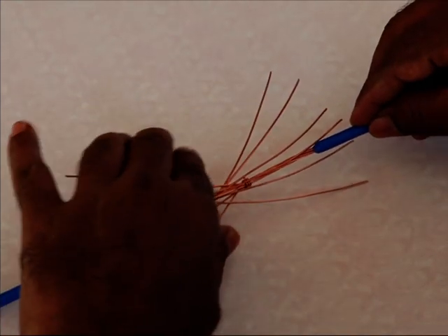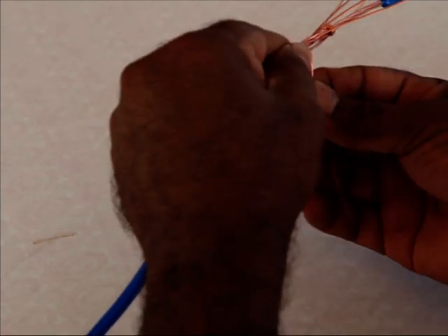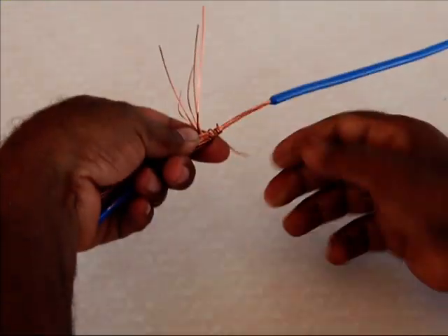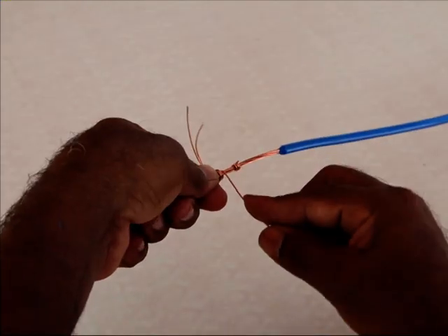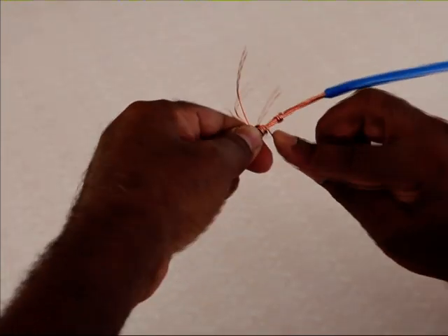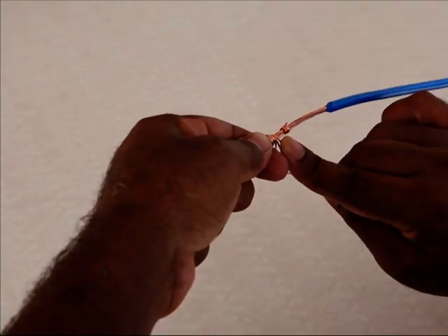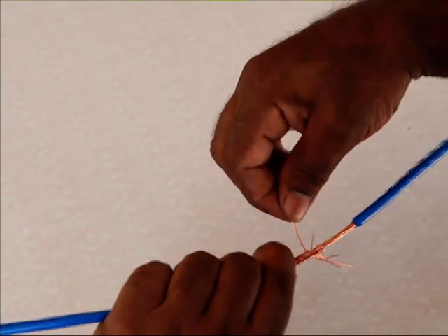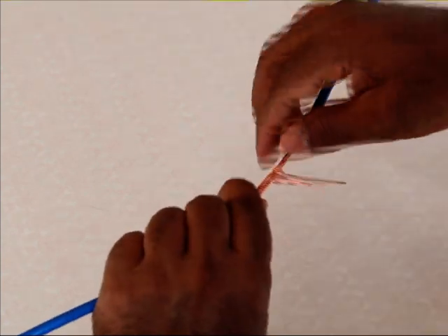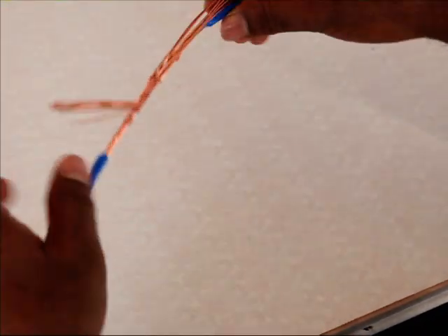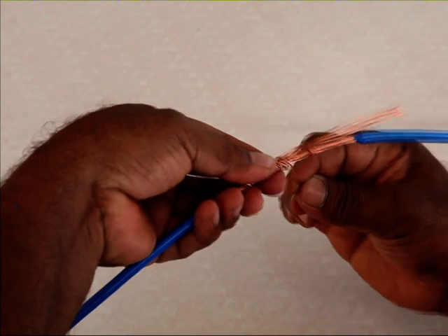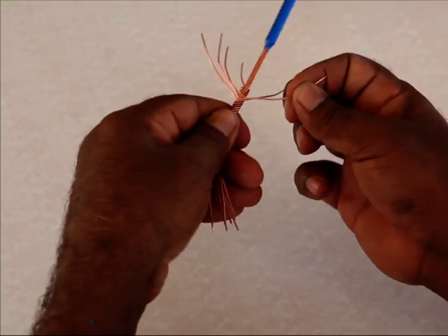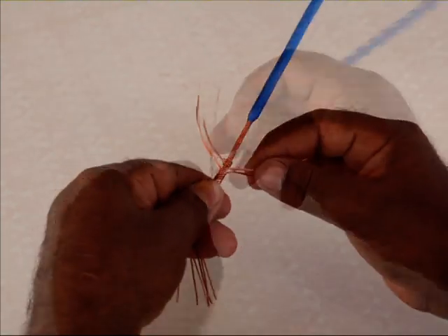8. Hold one of the cables in one hand and twist the strands of the other cable end over it, one by one, closely and tightly. In doing so, each strand has to be twisted half a turn at a time. Twist the strands of the other cable one by one. The direction to twist from the shoulder should be the same as the cable's original twist direction.